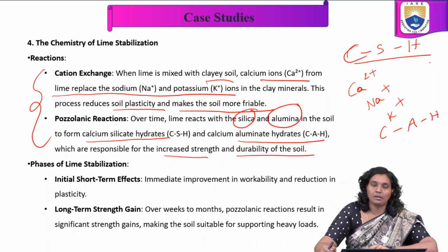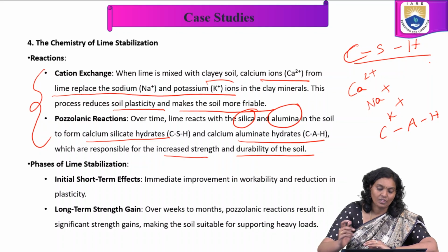Phases of lime stabilization: there are initial short-term effects and long-term effects. The short-term effect is the immediate improvement in workability and reduction in plasticity, because of cation exchange, the ions exchanging.